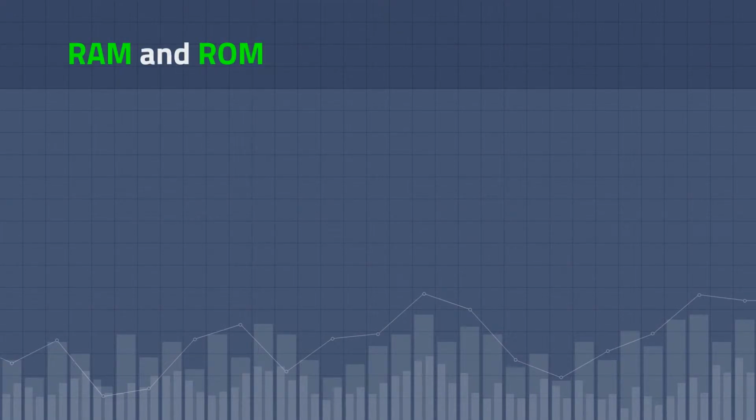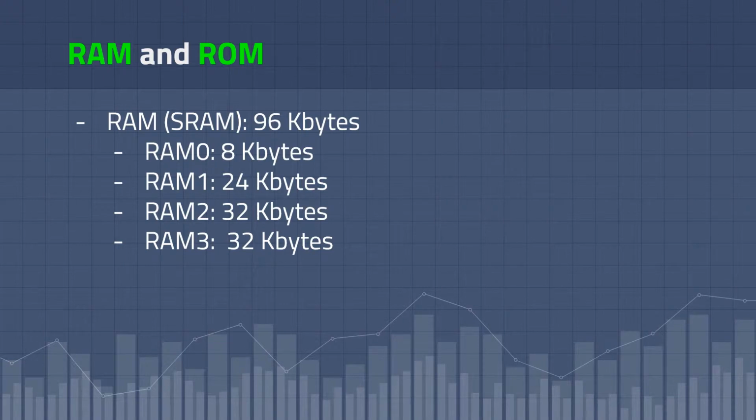RAM and ROM. RAM is random access memory, which is volatile memory used by the CPU to quickly access and use information that will not be stored permanently. When the device powers off, any data in RAM will also be wiped. In the MC1322x, the RAM is divided into 4 blocks of RAM: RAM 0, RAM 1, RAM 2, and RAM 3. This allows the unit to save power. Individual RAM blocks can be powered off while the device is not in use.